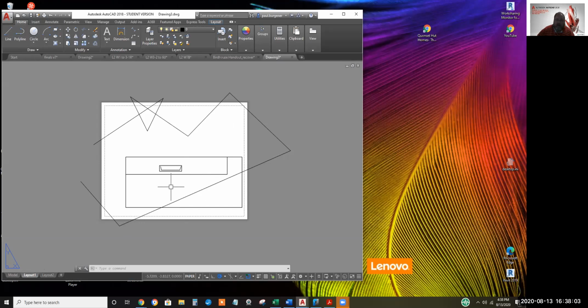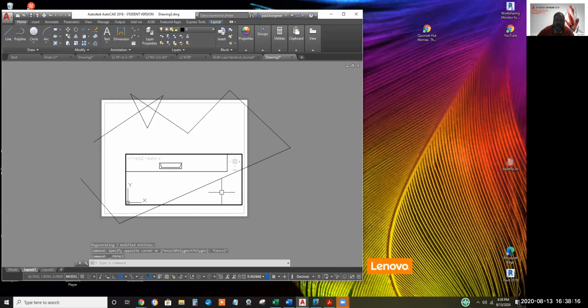The quick way to get back and forth between your hands inside the storefront and outside the glass is simply by double clicking in or outside. And double click there, and that made the viewport bold. I no longer have the blue triangle here in the corner. I got the old familiar UCS icon that you're familiar with from model space work. And the status bar says model now.